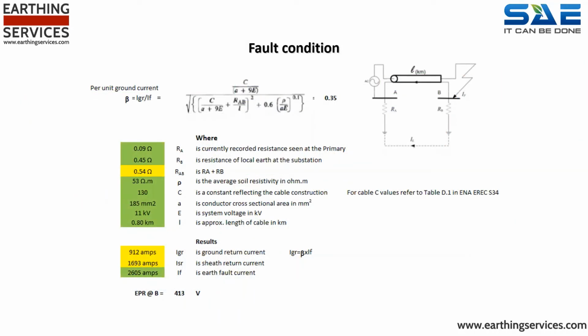So now we know how the ground mass will discharge electrical current. But what fault level might the earthing system have to manage? This sort of information is provided by the respective DNO. In this instance, the DNO advised that the maximum 3-phase fault level was 13.122 kA, the 1-phase fault of 2.605 kA, with a fault clearance time of 1 second.